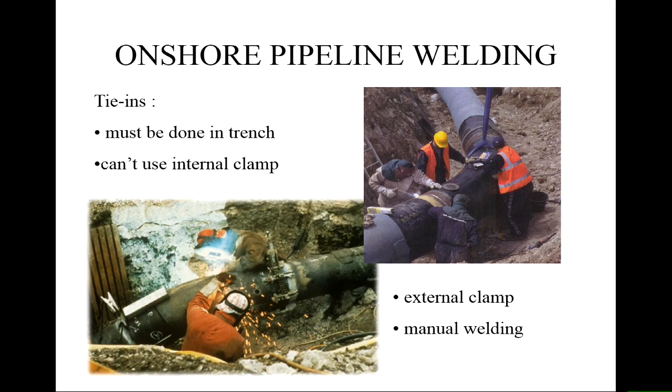Tie-ins must be done in a trench. So if you thought it was hard to get at the bottom of a pipe when it's chopped up on supports, imagine doing that standing in the water in the bottom of a trench, working underneath something which has been excavated. It can be done, the same processes pretty much can be used. The clamping arrangements are somewhat different. You can't usually put an internal clamp in, so we have external clamps and systems for holding everything together.